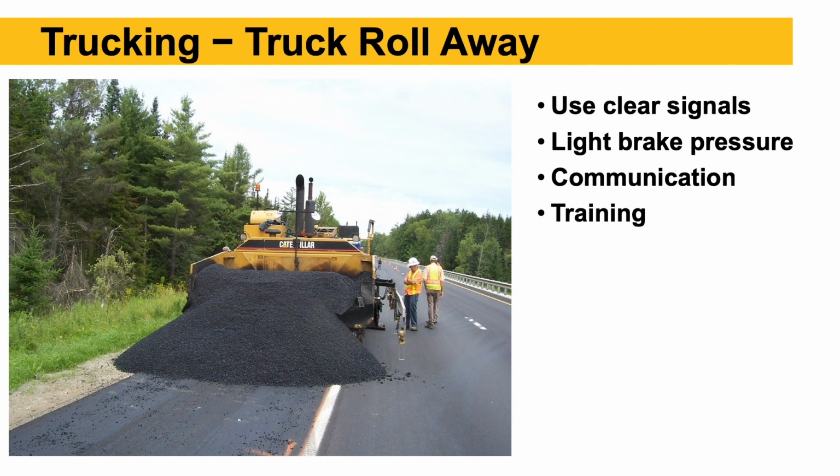This picture, you can see what happened. Truck rolled away from the paver, and we've got a very unhappy crew. So we want to use clear signals. Whether it's a dump person giving signals to the truck driver, or in a lot of cases it's the paver operator giving signals to the truck driver when to raise the bed, apply brake pressure and all that. But good communication and training is really key to a good truck exchange and mix delivery into the hopper.